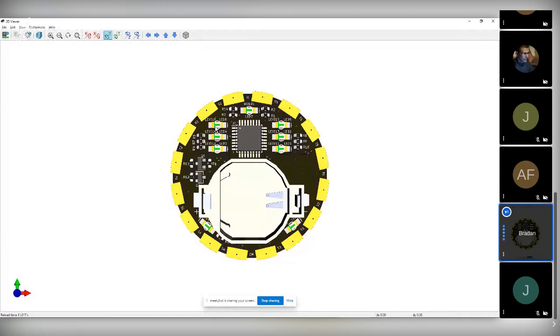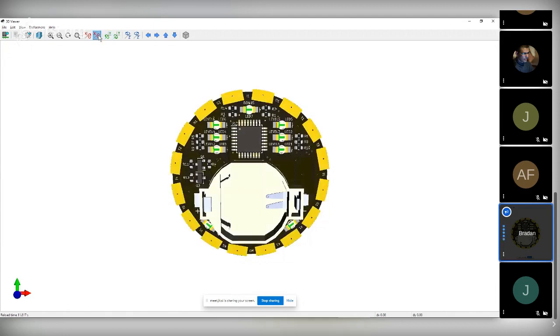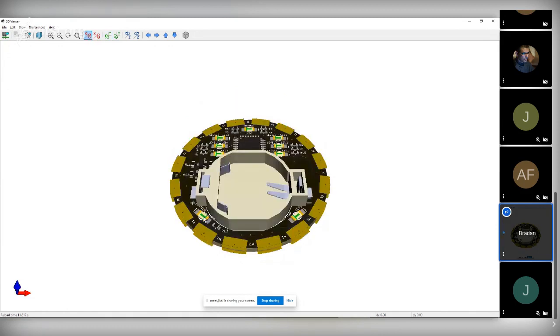pad A or pad 1 and pad 2 that extend quite a ways out from the side of the actual LED. A lot of people have actually just taken regular LEDs and mounted them upside down, but these LEDs were actually designed to be mounted upside down, and they work quite well, but they're not a commodity item at the moment. But you can get them in almost any color. You can also get, you'll notice, I think if I can just flip this a little bit the other way, you'll notice I actually have infrared and photo transistors in the same version down here.